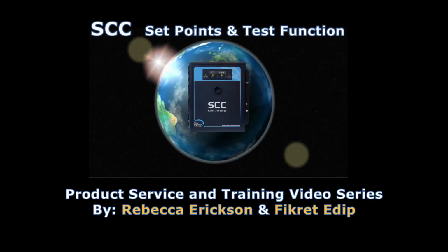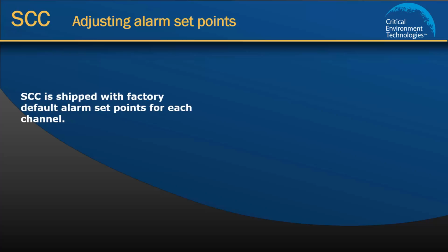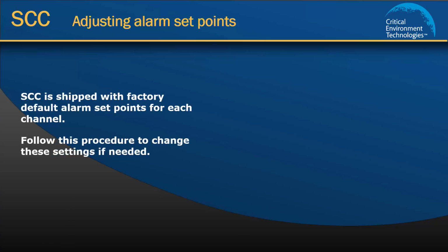In this tutorial, I will demonstrate adjusting alarm set points, setting relay on-off delays, and performing test functions. Adjusting alarm set points. Each SCC is shipped from the factory with default alarm set points for each channel, but you may want to change these settings.